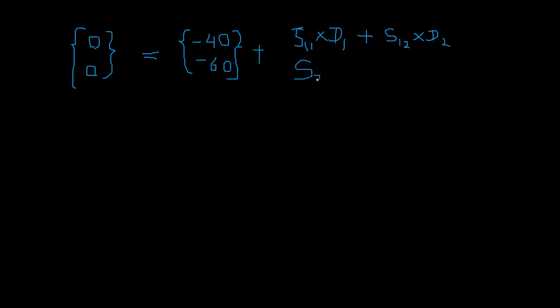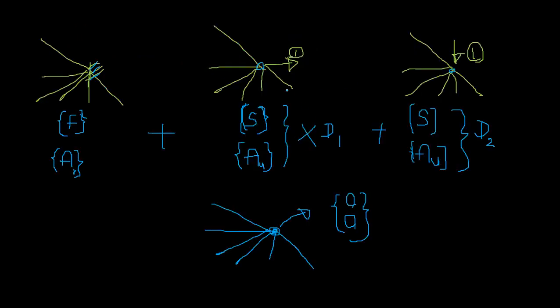Here it is S21 into D1 along this second direction, because you apply D1 in the first direction, you apply a unit displacement and multiply everything by the actual deflection, right?